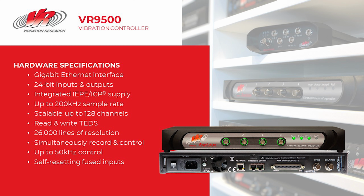Its inputs also have 200 volt tolerant self-resetting fuses on the inputs to protect the controller from high voltage transients. So if you accidentally threw power at one of the inputs, the box itself would not be used as a fuse. There are fuses on each one of the inputs themselves.